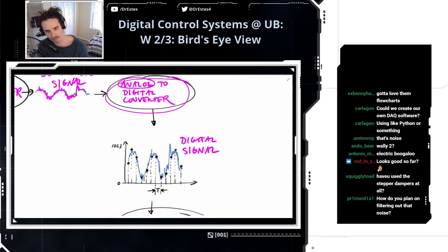obviously, but it has some logic built in there, and it's always taking in the sample and making some comparisons and saying, okay, which bin is appropriate? Like, what discrete level is this voltage closest to that I can throw it in? You can see that on these labels, I put a range of 0 to 1023 integer values. So it's always being sent to an integer value in between there. And you'll see why I picked these numbers in just a second.